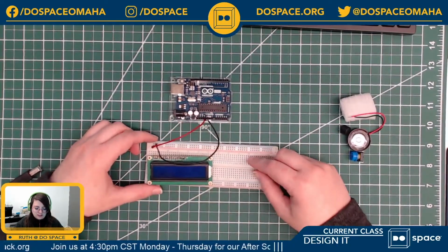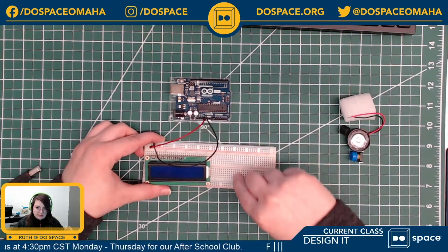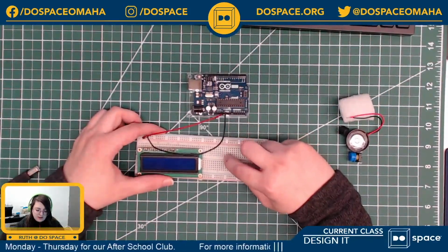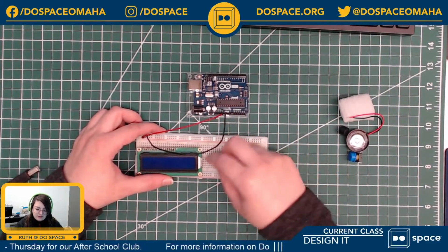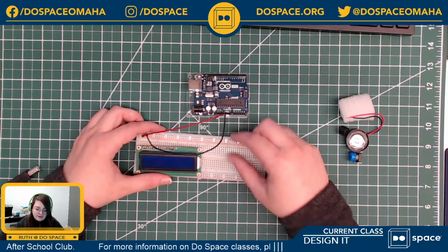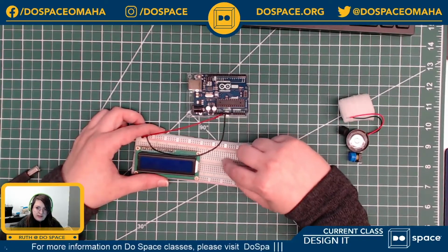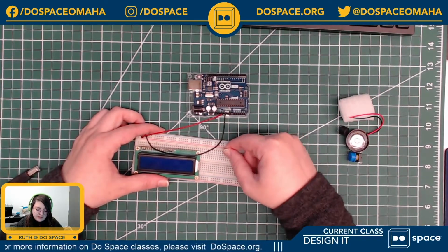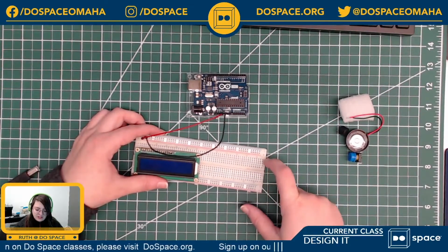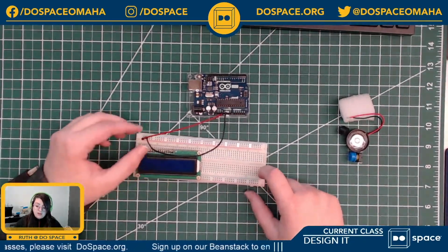So how this works is that anything the same at the shorter line, I don't want to say horizontal or vertical because you can literally turn this any way, but the shorter line within this line right here, like this is cut into two breadboards technically, so this is one breadboard and this is another. So here's one, so any of these five, six holes in here is one line, those are connected, but things in the long way from one to the other, the numbered lines, actually the A, B, C, D lines right here going from left to right are not connected. I'm about to lose light.